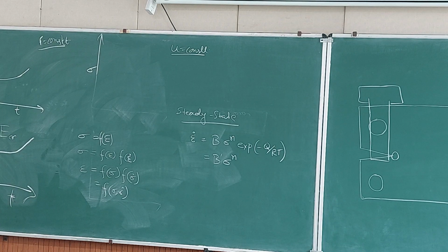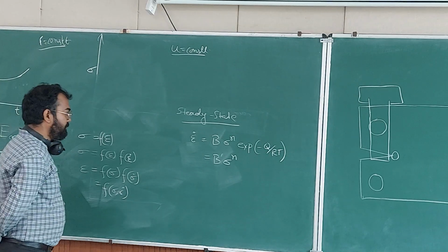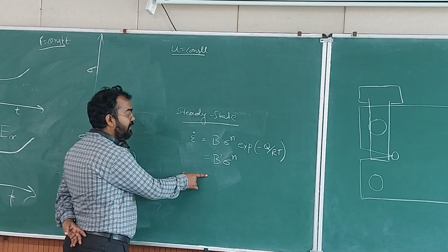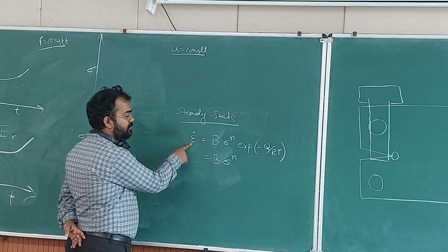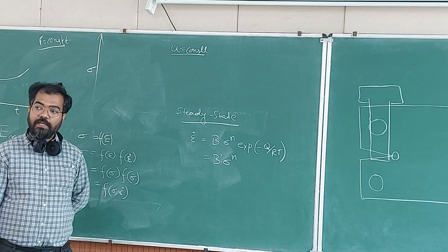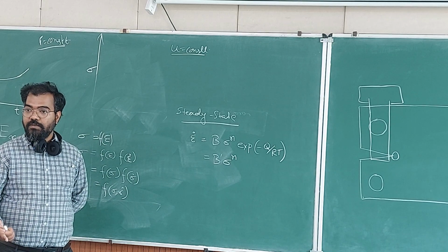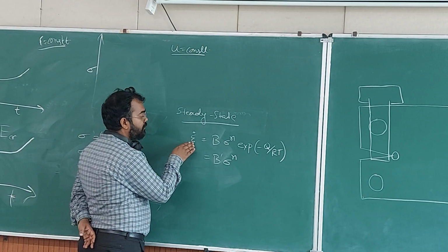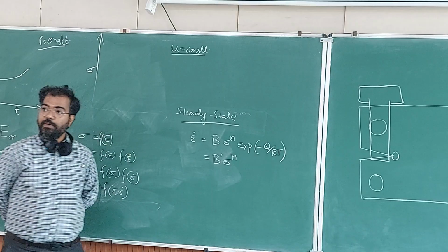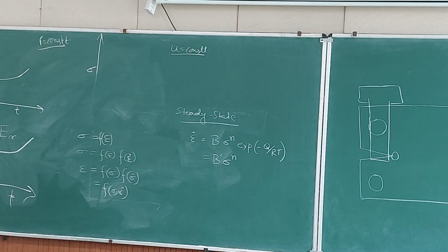So it is only a function of stress, isn't it? Right? So when this happens, you can probably define a new integral where you will have to use strain rate instead of strain, because we are not getting a relationship between stress and strain as a single-valued function, but we are getting a function between strain rate and stress, like the Ramberg-Osgood equation.